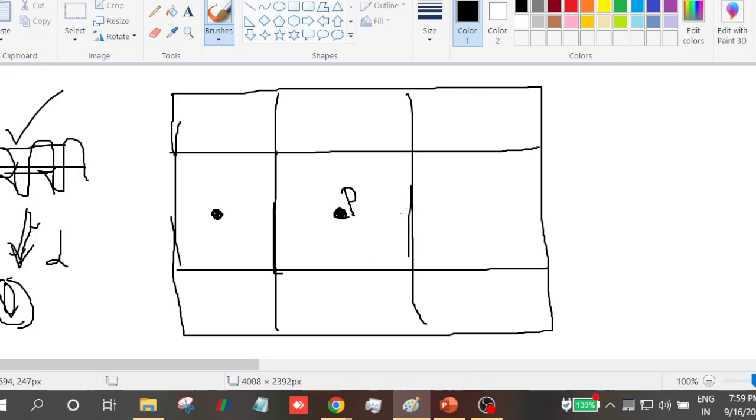Now what we do is that since we need the pressure gradient at the faces, we make this centroid only as a face. The next centroid will come at E. So for x momentum I want at east face and west face, so I'll make this only as face. That is done by storing the velocity at the face of this control volume, and defining a new control volume for x velocity, which I'll indicate by the solid lines. So this is how I define the storage of new x velocity.